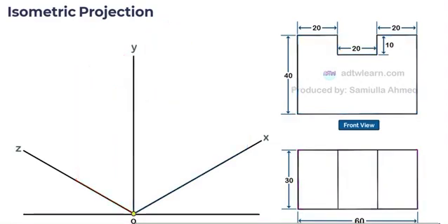Let's start drawing. We will name the edges of this front view for our convenience: P, Q, R, and S. We will draw the front view of the object facing on an xy plane. Therefore, while drawing, we will consider this left edge point of the figure as at this intersection point. Therefore, label this intersection point as P. Consider this xy plane.